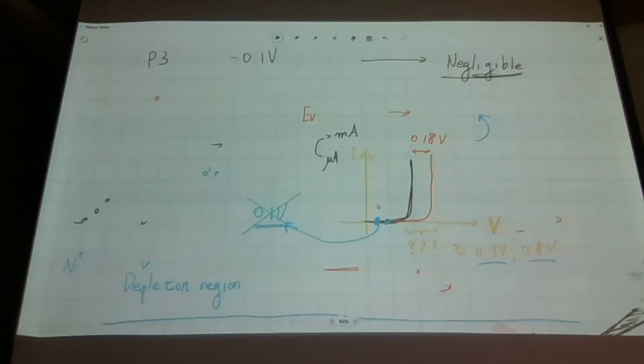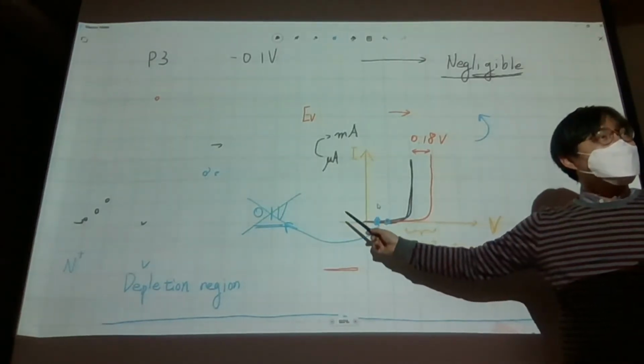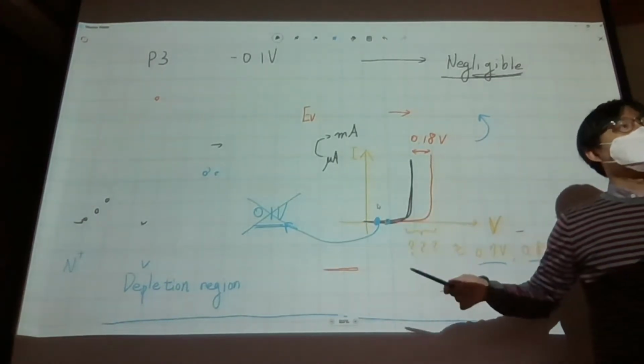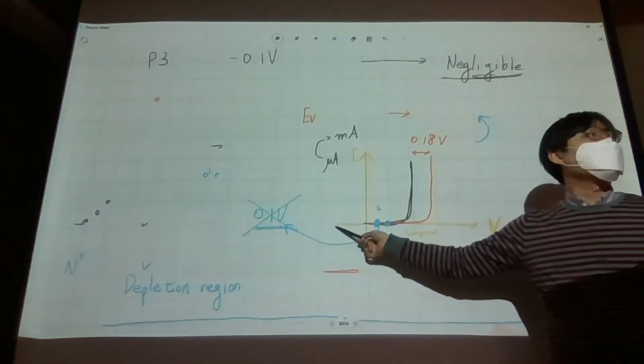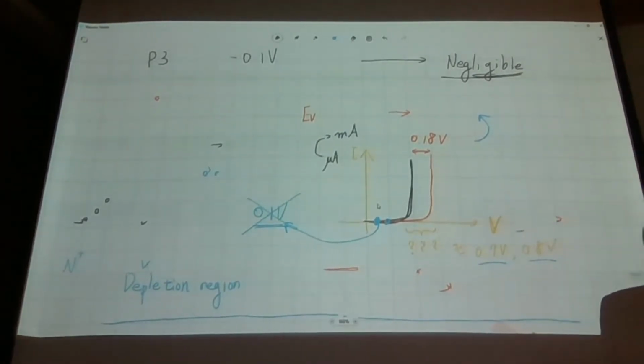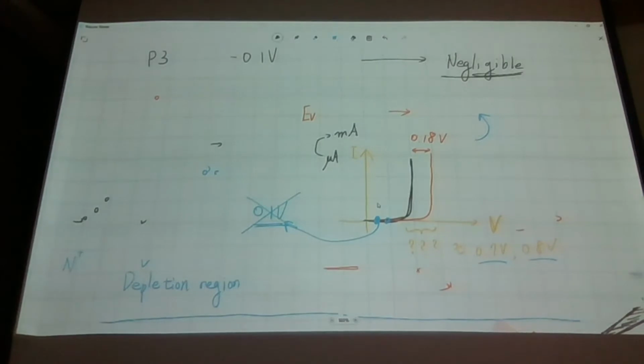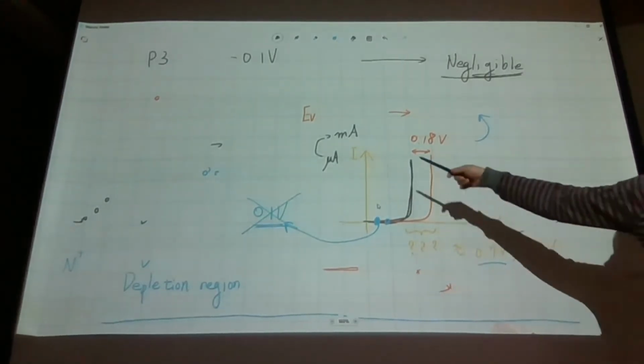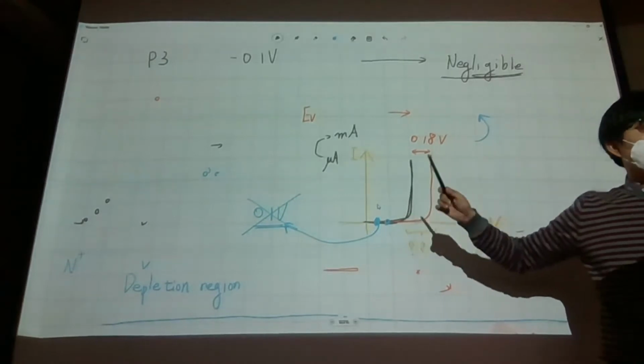So, today's lecture has been devoted to the description of the IV characteristics of our system called the PN junction, and we have considered the reverse bias and forward bias. Interestingly enough, we have a completely different behavior when we have a really negative or reverse bias operation. Then we have almost vanishing current, although not exactly zero, but it is several orders of magnitude smaller than our usual application window.